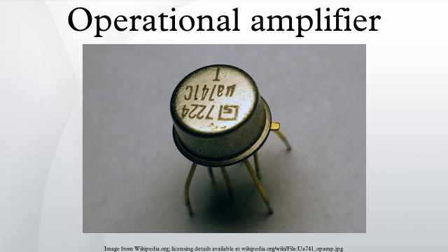Note that a device designed primarily as a comparator may be better if, for instance, speed is important or a wide range of input voltages may be found, since such devices can quickly recover from full-on or full-off states. A voltage level detector can be obtained if a reference voltage VREF is applied to one of the op-amp's inputs. This means that the op-amp is set up as a comparator to detect a positive voltage.